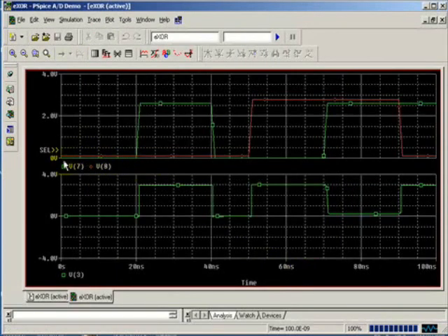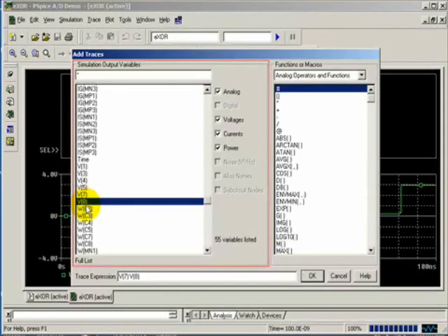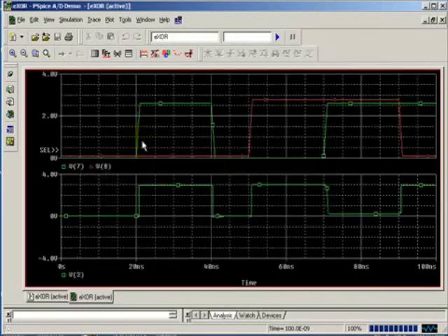Here, in the first 20 nanoseconds, both inputs are the same, low, so the light should not be on. In the next 20 nanoseconds, the 7 and 8, one is low, the other one is high, so the output should be high, or the light is on. The next 10 nanoseconds, the inputs are both low, so the light goes off because of the change of the input.